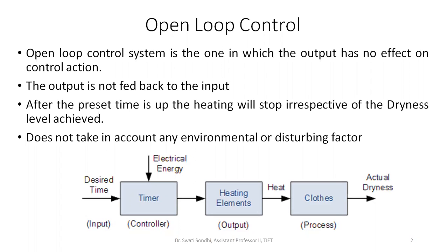And there is no way in which we can actually monitor whether the final output has been achieved or not. So this kind of a configuration that you see, this is open loop control. Okay. So ye configuration, this can be useful only for small systems where everything is predetermined. When you know that okay, whatsoever type of situation might be, if I set the controller for 20 minutes, I'm sure that it is going to get dried up. So if all the data, everything is known beforehand, and you know that this much timer is going to work, then of course you can use this kind of a control system.